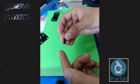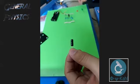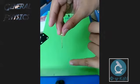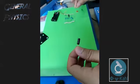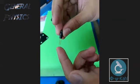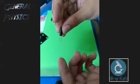If it is polar, it looks like this, with a longer leg. The longer side is always positive. The one I have now is non-polar, so it can be connected either way. If one leg is longer than the other, that's the positive, so it cannot be reversed.